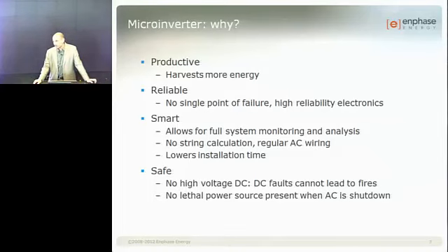We don't need to do string calculation. On a string inverter, you have to figure out how many modules you put in series and how many strings of series modules you put in parallel. It's not required. It's very simple, one by one. Anybody can do it. I can do it, so anybody can do it.